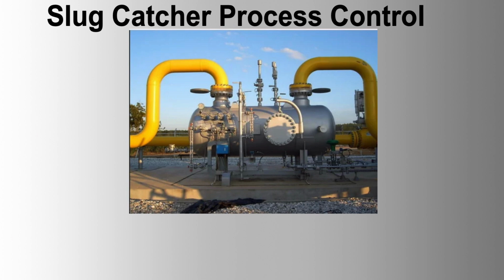Use a feed-forward controller to adjust gas outlet valves based on upstream pressure changes, and a feedback controller to fine-tune the gas outlet valves based on real-time pressure data. 3. Feed-forward and feedback liquid level control.